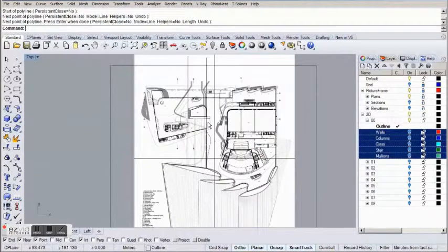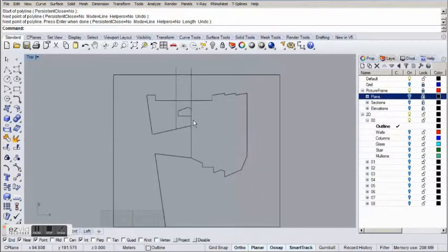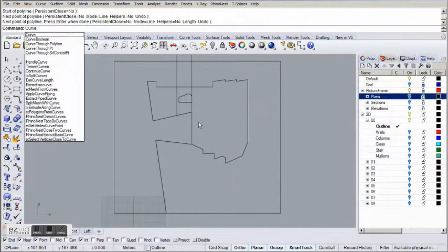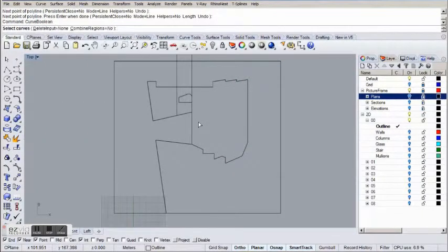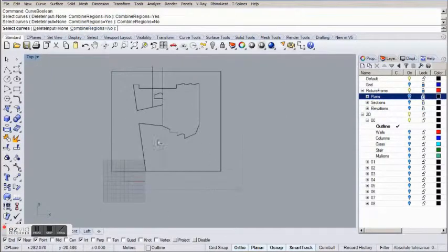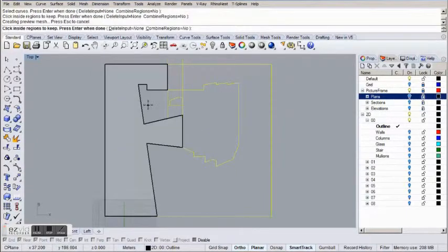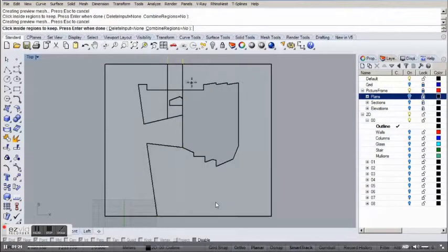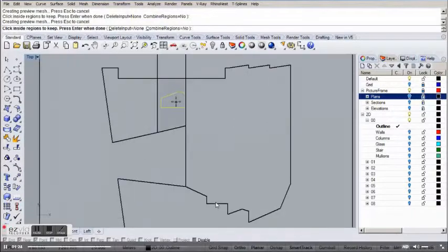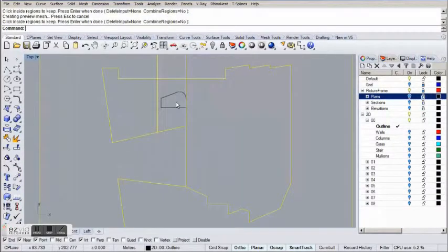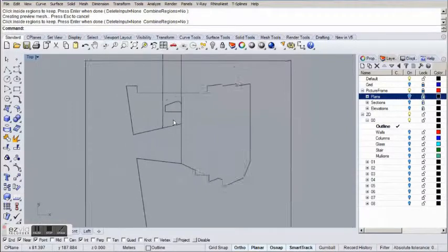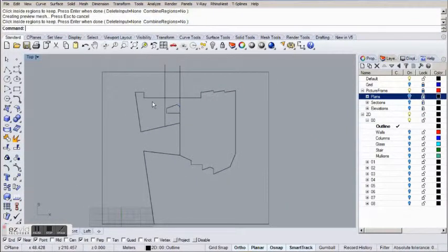Okay, cool. Let's use our Boolean curve command to acquire our new boundaries without going about splitting lines again. Make sure the combine regions option is set to no. Okay, nice. Let's delete the double line parts we don't need anymore.